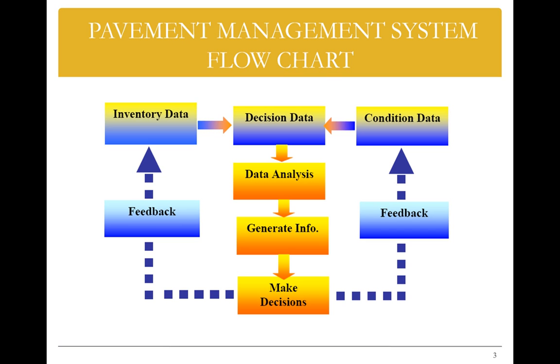Here is where the data analysis would help you to define that the section with continuously increasing fatigue data indicates that there was no additional maintenance over the years, while the other section that had improved fatigue cracking over time indicates that some maintenance happened that decreased the fatigue cracking all of a sudden, and after several years it picks up again.